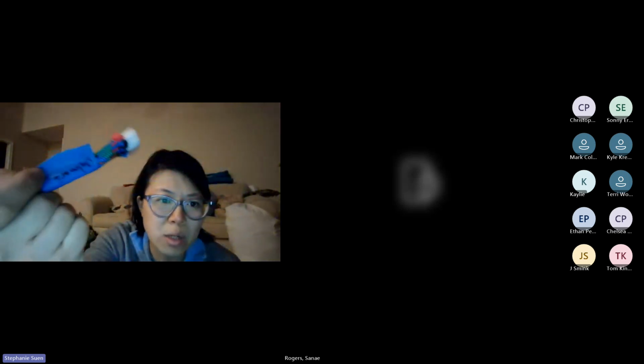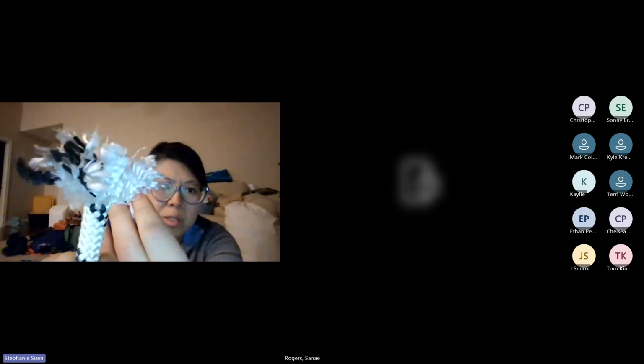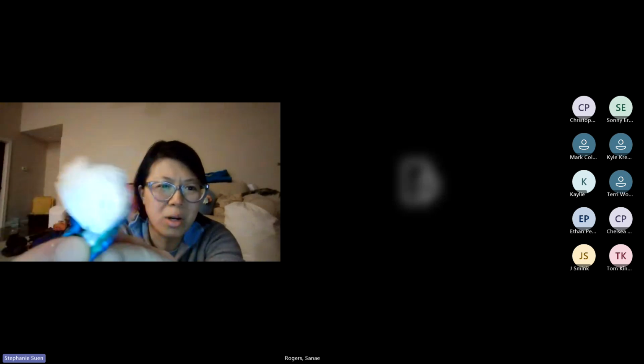And while it looks like it's a kernmantle rope because it's got an outer sheath and then an inner core, if you actually pull the core apart, these are plastic fibers. I can't tell you if it's nylon. You can see it's not braided, they're just loose fibers, versus if you look at my actual PMI rope here, you can see there's some weaving going on there. But this is plastic fiber, and then you get to the rest of the core and that's tissue paper.